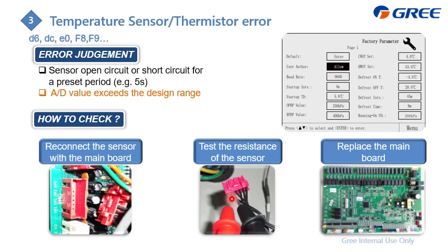For the service person, we always bring a good sensor with us, and then we just put the good one near the suspicious one and compare the resistance of these two. If the difference is not that large, that means this sensor is okay. Otherwise, you need to change it. So with this method, we don't even need to know the temperature. Just compare the resistance value. It's okay.